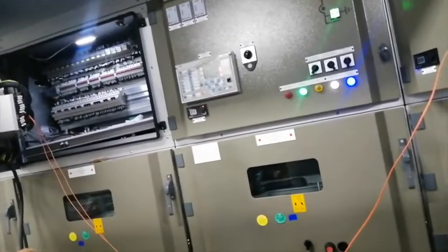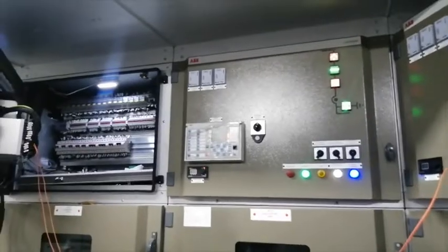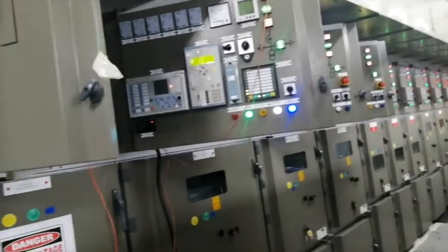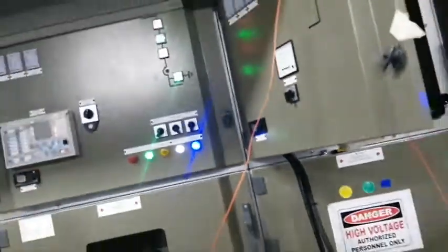So actually, all these are different conditions of only one signal. That one signal is 132 kV circuit breaker close permission. So multiple conditions are there in this signal. One is that the 11 kV circuit breaker should be in service position, that we checked. Second was that there should be no fault, that we have also checked. And what else? Then we have checked that the circuit breaker should be in the open state. That also we have checked. So through different conditions we check this signal, 132 kV circuit breaker close permission.